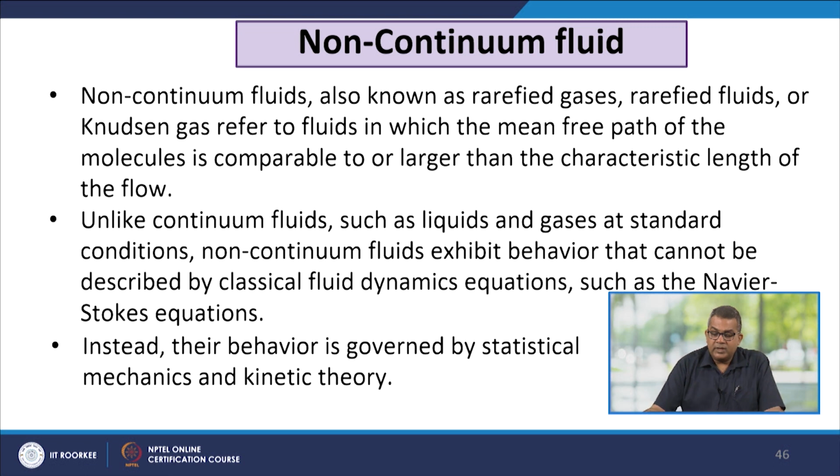Non-continuum fluids, also known as rarefied gases, rarefied fluids or Knudsen gas, refer to fluids in which the mean free path of the molecule is comparable to or larger than the characteristic length of the fluid. Unlike continuum fluids such as liquids and gases at standard conditions, non-continuum fluids exhibit behavior that cannot be described by classical fluid dynamics equations such as the Navier-Stokes equation.